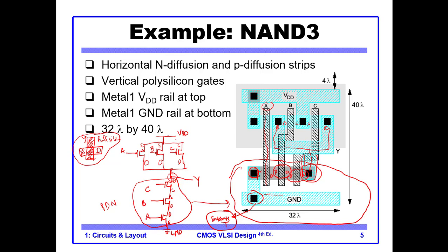You may ask how I select on which side is source and on which side is drain. Basically, if you look at the transistor, the drain and source are symmetrical. You can call one source and the other drain, it doesn't matter. It only depends on your supply. So you connect the supply to the source, and the drain is used for interconnection. It is used for drawing the current. So it doesn't matter, you can swap the source and drain. Okay.